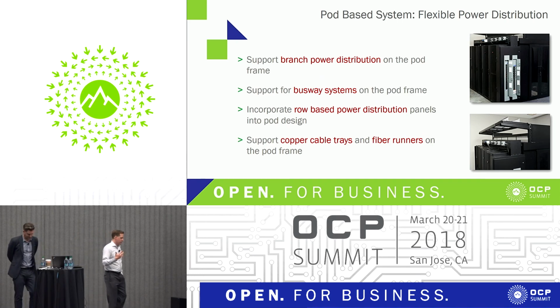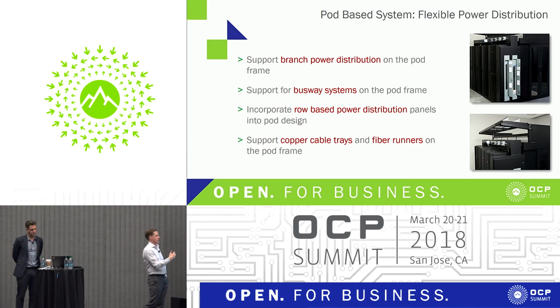Another best practice, I would say, is to be able to adapt to different types of power distribution. So depending on the density of a certain pod or the country you're in, you might have a different optimal power distribution. So to be able to adapt to that, to have a panel board that's mounted on the pod, to be able to hang a busway along the length of that pod, to do in-row power distribution, depending on what's really the optimal for that deployment. And then again, to be able to support all that copper, fiber, cabling right on that pod structure just makes all of that distribution a lot easier.